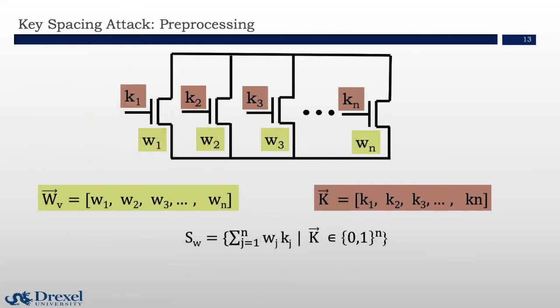For the preliminary evaluation, from this analog circuit netlist, all the obfuscated transistor width information is combined in the set WV. Based on the set WV, all different combinations of the bits are calculated and inputted into a set SW based on the equation.